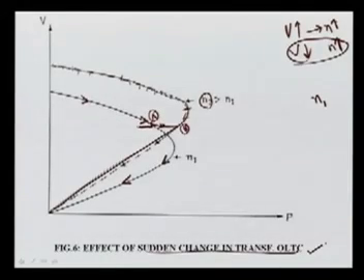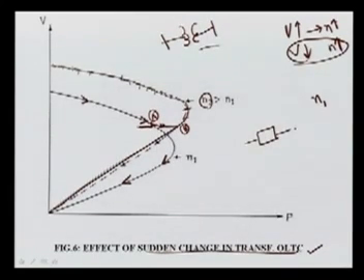Now, let us see why this is happening with the OLTC. This voltage stability problem is related to the reactive power of the system. Because of the tap changing, you know that a tap here is nothing but a transformer, let us suppose, and if you are having some taps here, this transformer can be represented by a pi equivalent here, with the shunt parameters here.